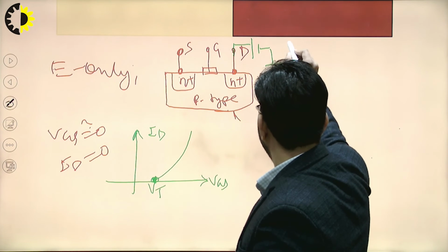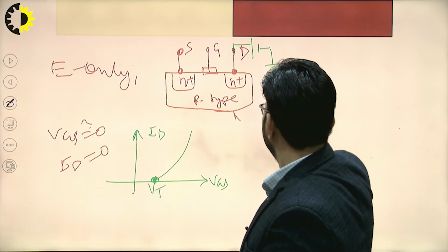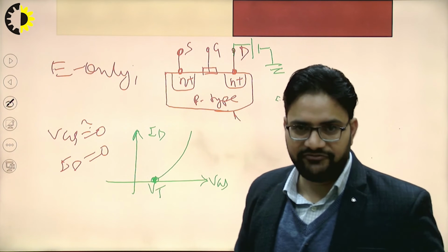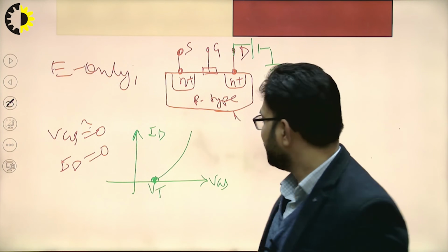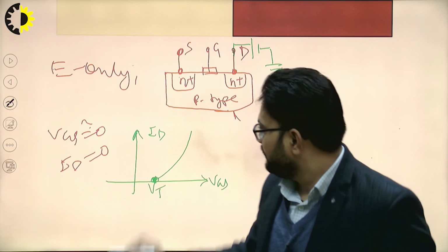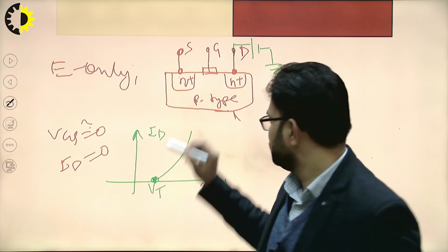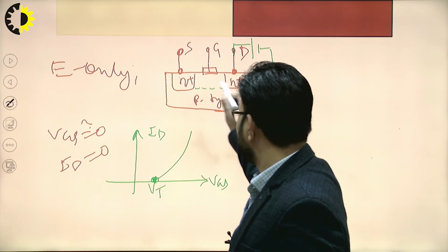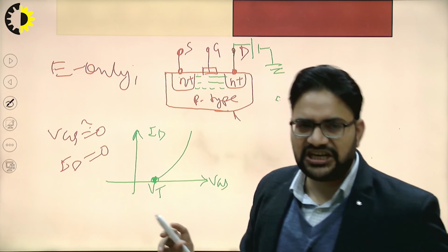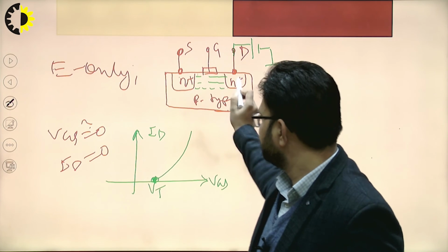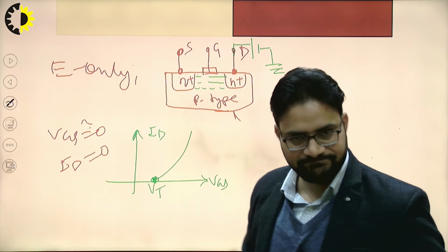So here we have plus minus VDS varying and VGS kept constant. In this case, for the proper gate to source voltage applied, a channel was introduced, right? So we are assuming that we are having the channel. So this is the channel actually, and charge carriers are moving from this place to this place, and drain current is flowing from this place to this place, right?